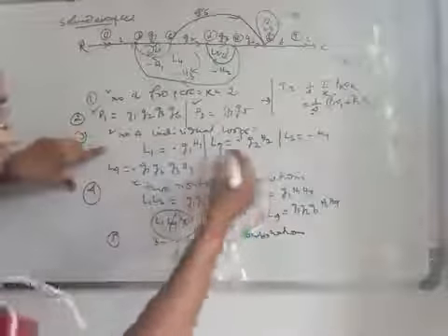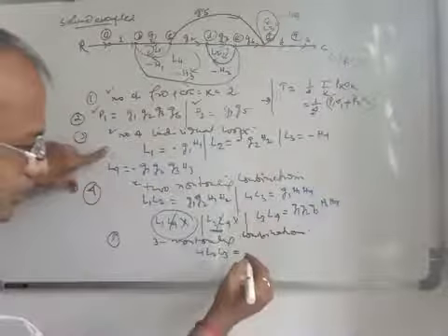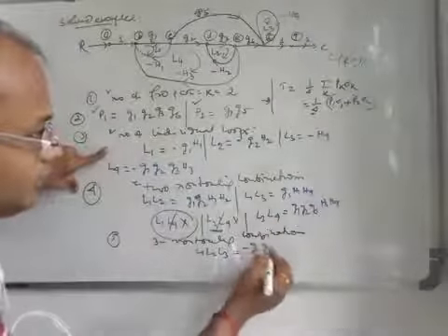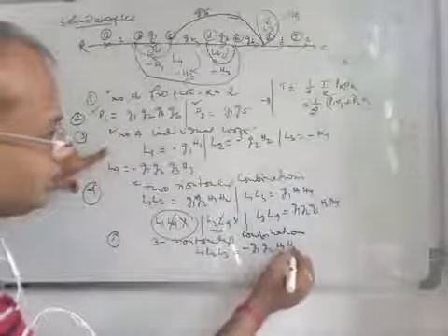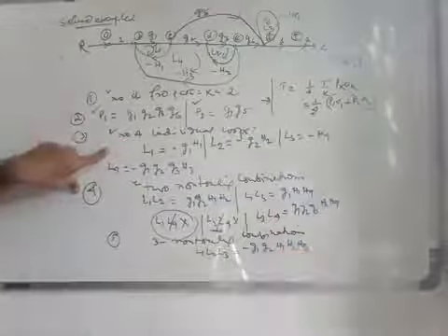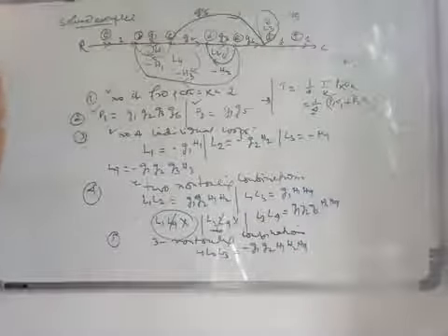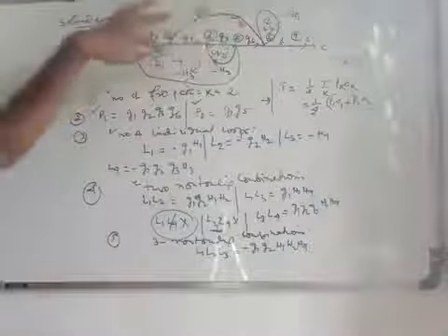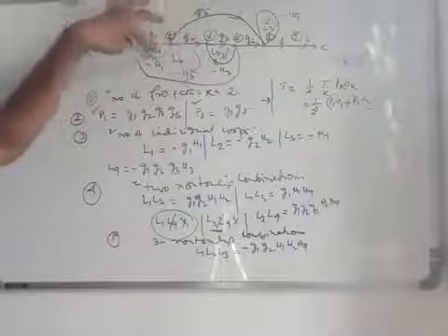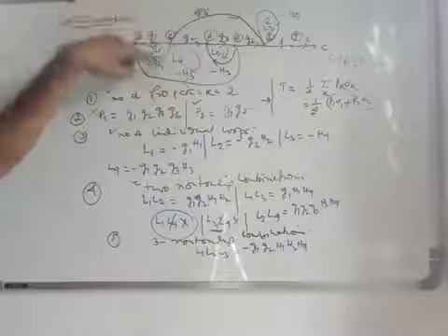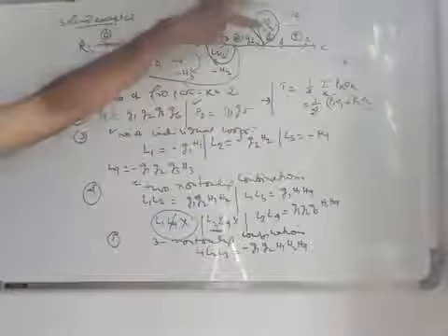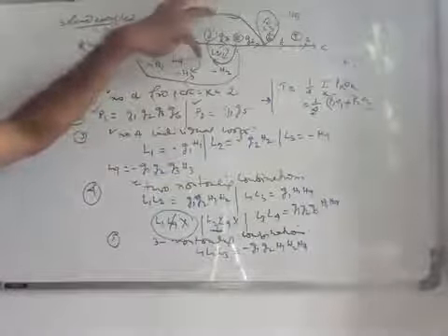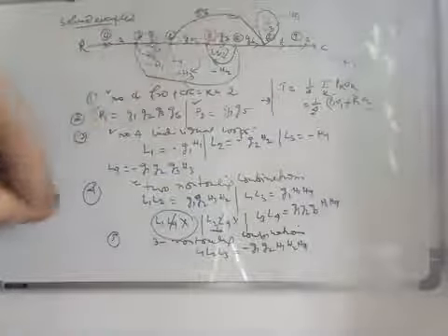If you multiply this, you will get the gain product. So this is minus G1, G2, H1, H2, H4. This is L1, L2, L3. Next, what could be the combinations? L1, L4, L3 is not possible, because L1 and L4 share a common node. L2, L4, L3: L2 and L4 share the common node, so L2, L4, L3 is not possible.